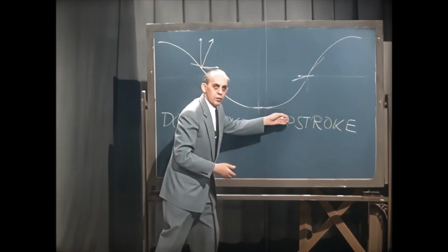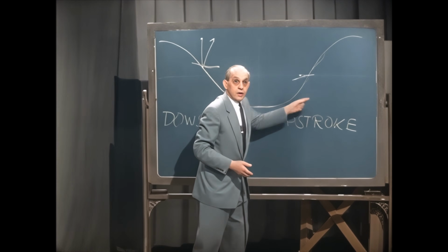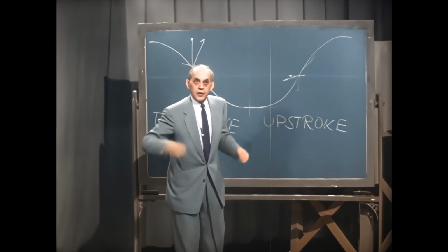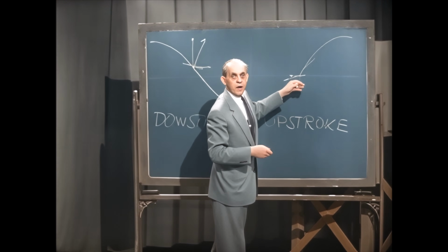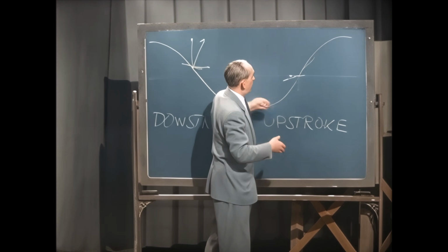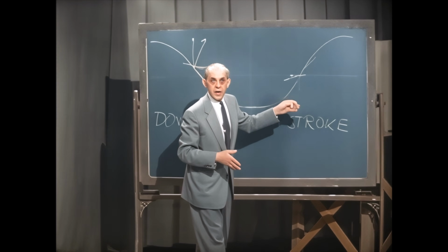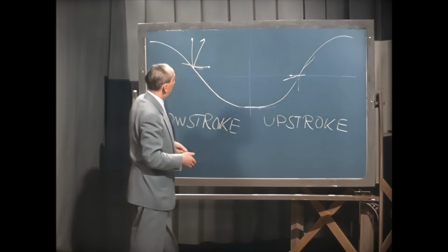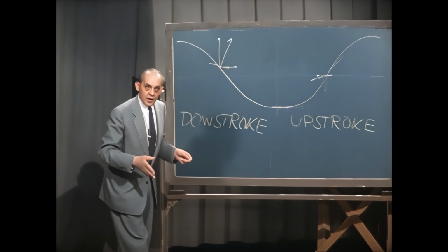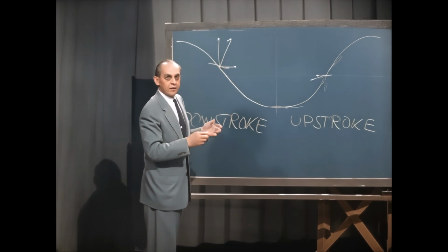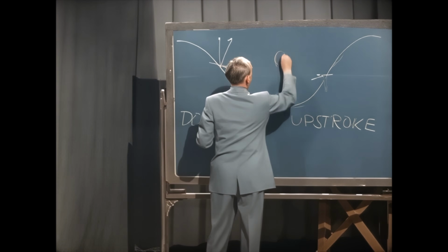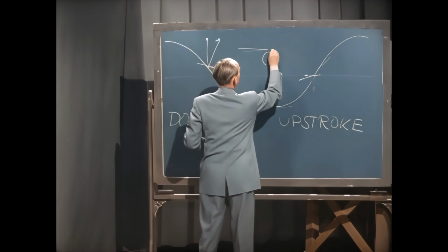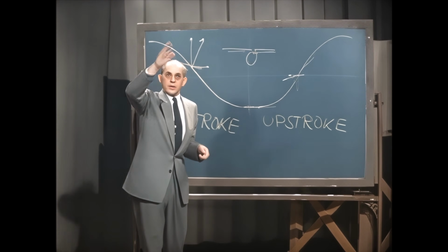During the upstroke, the trick is to move the wing in such a way that we don't have much drag and still maintain a certain amount of lift. Now, this is done with the bird in such a way that its center part of the wing doesn't move much up and down.